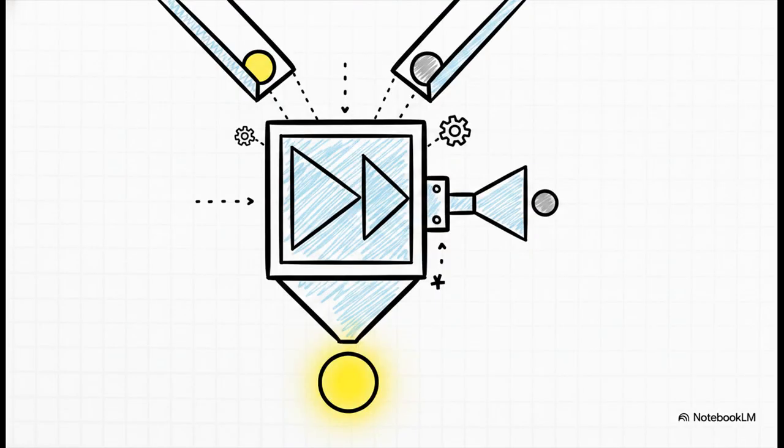To really see this in action, take a look at a half adder. If you want a computer to add two single-bit binary values, let's call them X and Y, you use a simple combinational circuit. Adding these bits produces a sum bit, which we'll call S, and a carry-out bit. The equation for the sum is literally just X exclusive or Y. It's just a basic logic operation. There's zero actual thinking involved here, right? It's purely hardwired logic, a physical circuit that naturally spits out the correct mathematical sum based on what you feed into it. Okay, now let's take those tiny logic gates and scale them up.